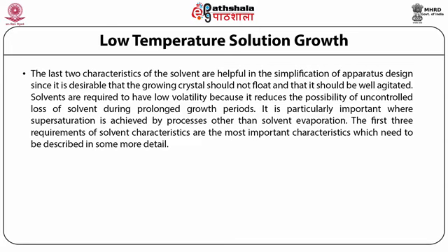Solvents are required to have low volatility because it reduces the possibility of uncontrolled loss of solvent during prolonged growth periods. It is particularly important where supersaturation is achieved by processes other than solvent evaporation.